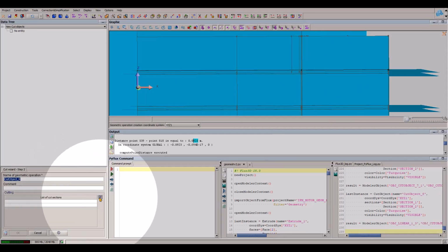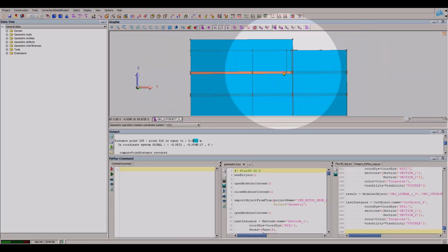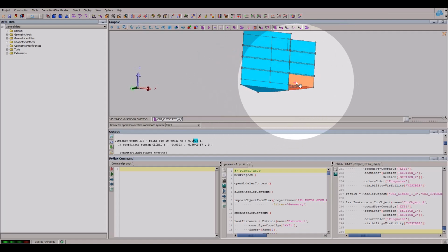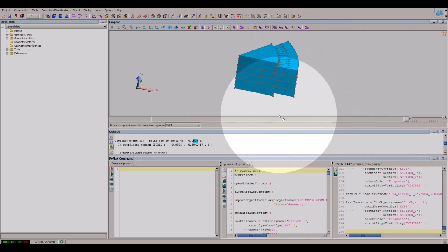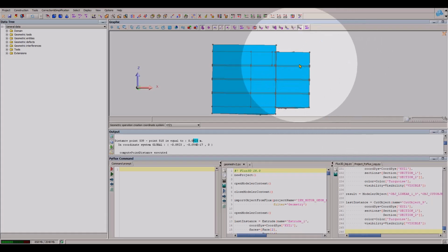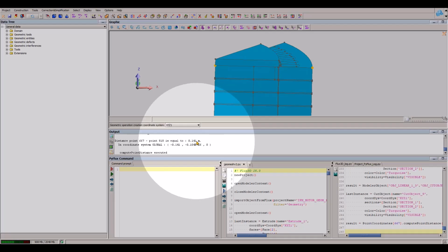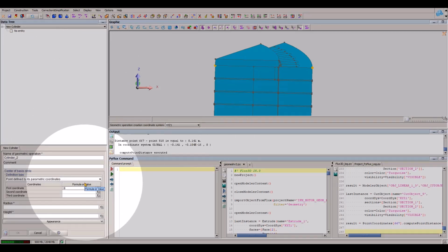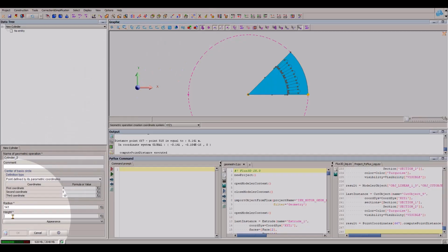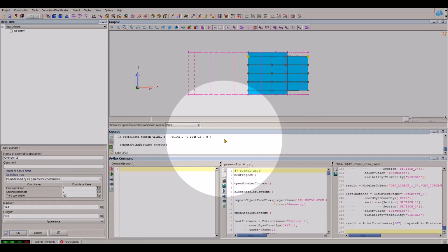Okay, now I will finish soon the cut of all the layers. Now I have a really visible junction layer that I am going to mesh in tetra, and the intermediate layer that I am going to mesh in extrusive mesh. To do that, I need first to make an assembly in order to avoid some intersection.